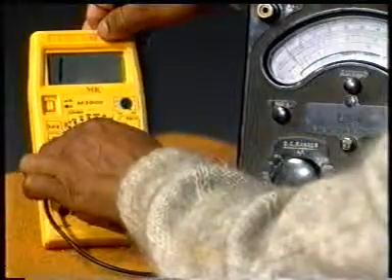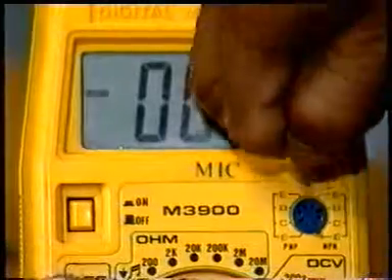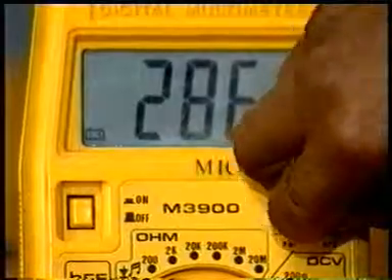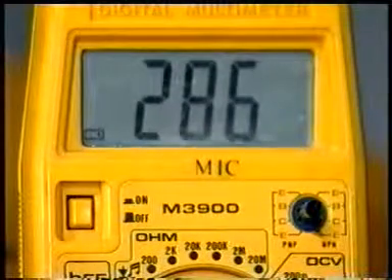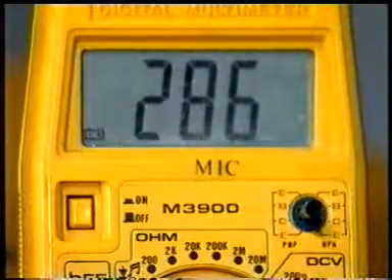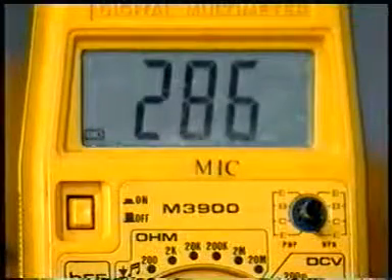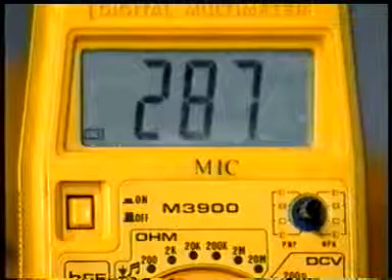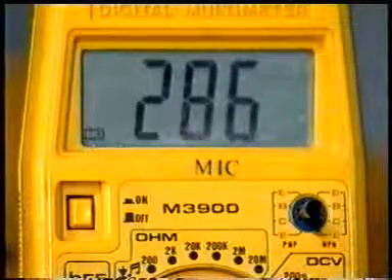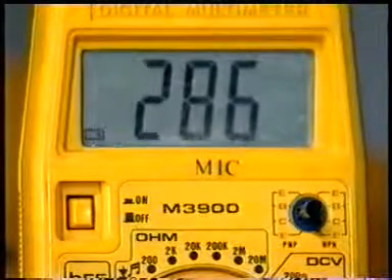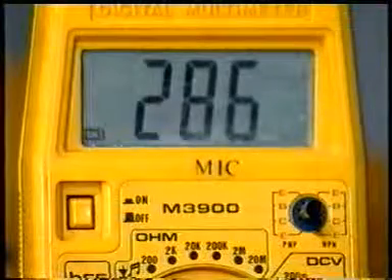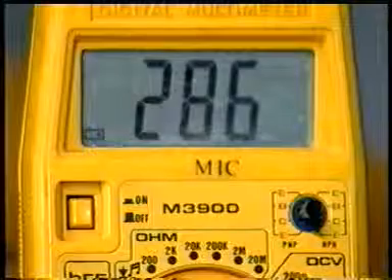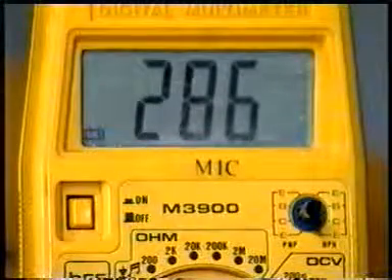Now there is another way of checking. You can find that there are two sockets on the digital multimeter. One is NPN, the other is PNP, and the terminals are marked on it. If you connect it properly, you can check it in HFE mode. He has placed it on HFE and it is showing some gain, HFE. If you connect the socket properly, then it will show, otherwise it will not show. So it is confirmed which type of transistor it is.